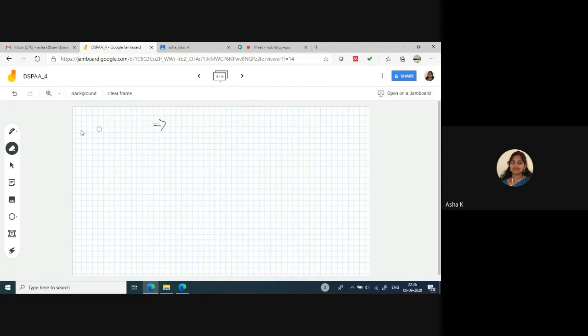For this FIR filter, the difference equation we are using is y of n is equal to 0.5 x of n plus 0.5 x of n minus 1. This is the equation that describes the finite impulse response filter, where x is the input sequence, y is the output sequence, and x of n minus 1 is the delayed version of x, or the past values of x.